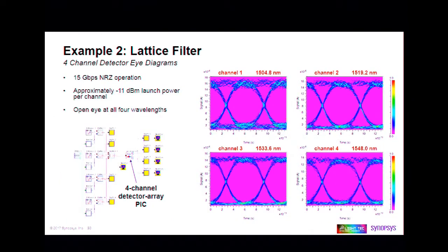And then we can test each arm of these filters and check the eye diagram for the 4 arms of the filter. And it's a pretty good eye diagram. It's quite open for each channel. So it's a way to validate the behavior of the filter, and then we can decide or not to go to the mask generation, to go to the foundry with this mask.